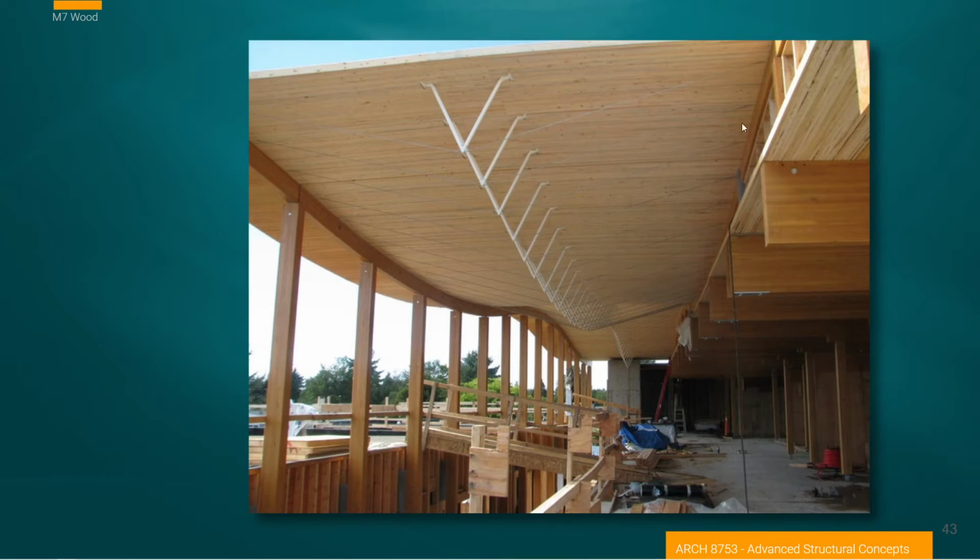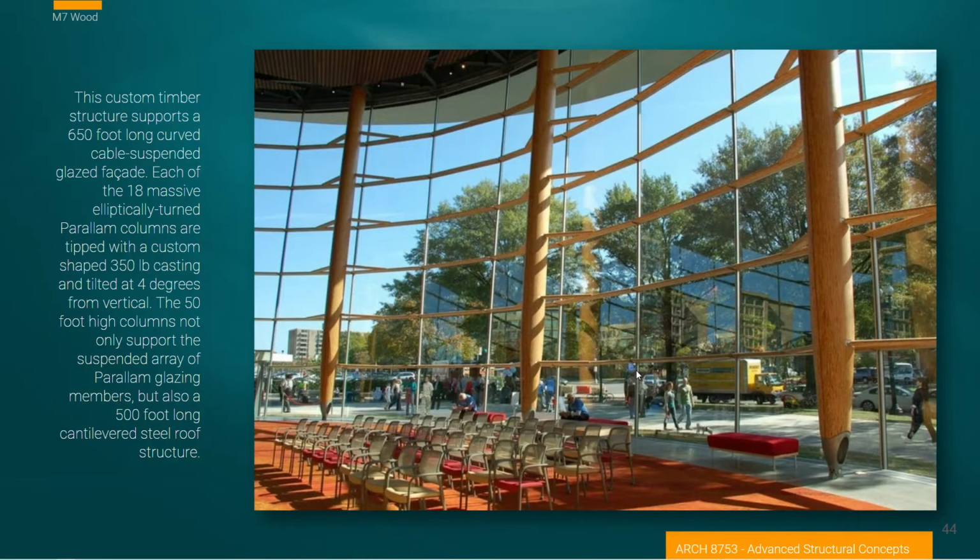One of the notable things about this one is we have a mass timber spanning a large area. And in order to give it extra strength, they put these struts on and then cable tension this. So now we have basically an inverted bow truss with the steel working in tension here. And obviously this has a nice undulation to it, and a nice front end undulation with it also.